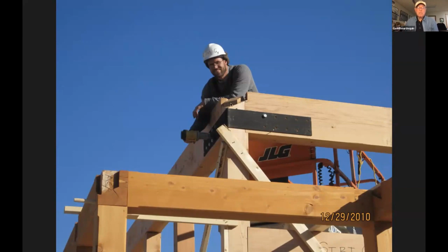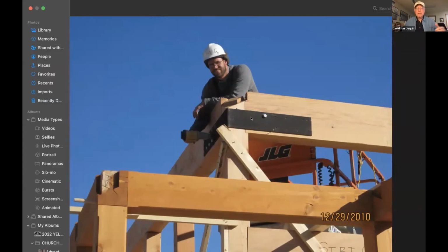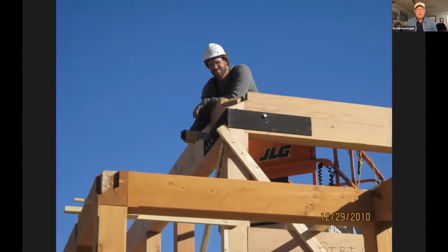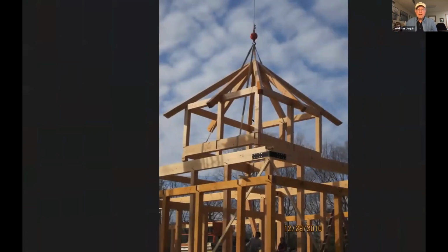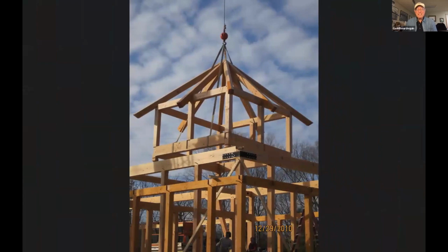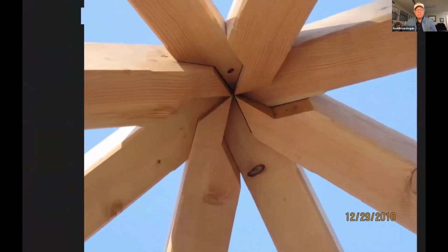You can see the top of the corner post cut off here to have a housing to engage that rafter, so that thrust goes into the post, and the post is trying to come out of the screen and toward your left, and these straps keep everything retained. And that handsome fellow looks like he needs a break. That looks like hard work to me. Here you see the strap in place going around this tension ring at this level.